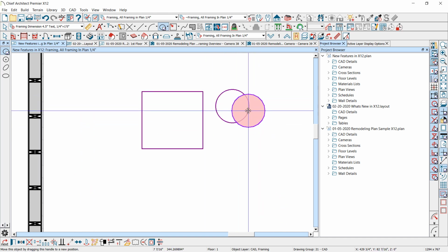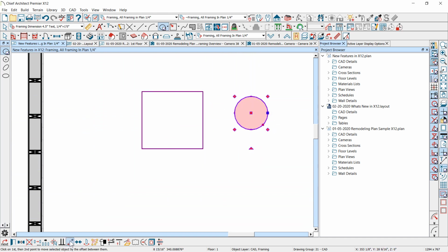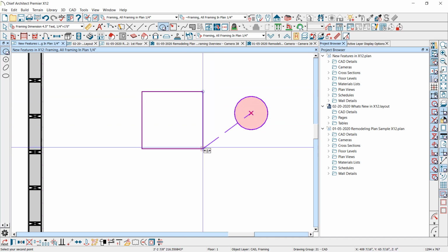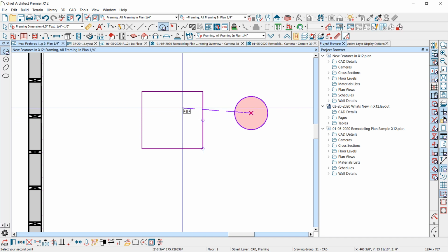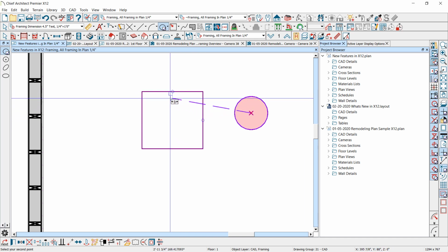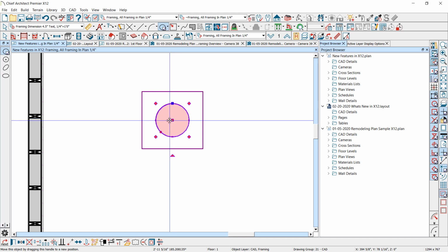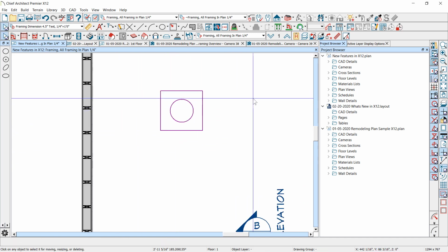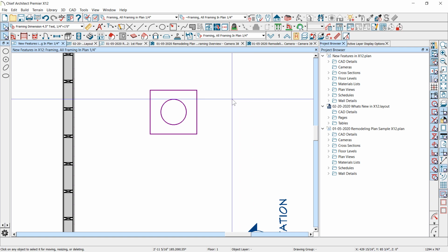So when I click on this, I've got my point-to-point move. By the way, I've set up a hotkey of S for snap. I'm going to click on the center. Now you see that visual line, so you can see where it's going to move that point from. So I want to get it in the center of that box. I'm going to click here, come to the center. Bam, that item's now centered perfectly in the box. That's a nice feature. I really like that a lot. Yeah, the visual move. Now you can actually see what it is you're moving.